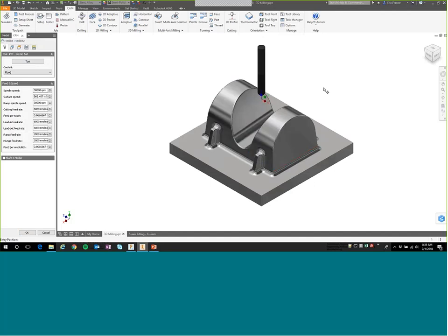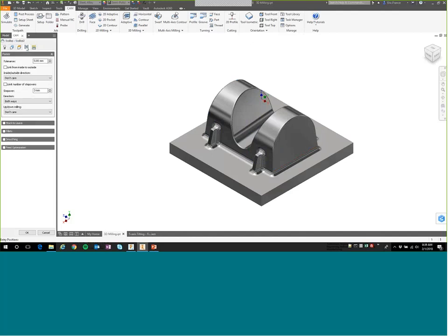Right, so we've identified that smaller ball, and the geometry it's going to pick up automatically, so we want to make a couple adjustments to some of the pass settings that we have in here. We want to go from the inside out. We do want to control our step over and have stock to leave.